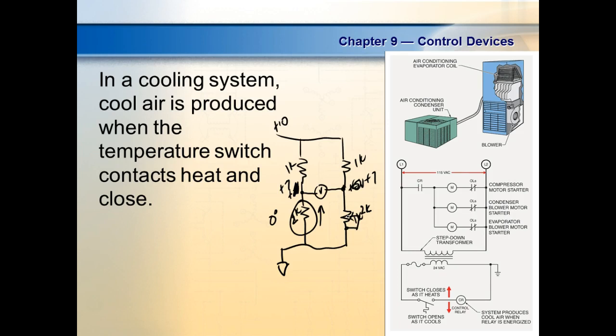And then if the temperature went down, my meter would measure minus. If my temperature went up, my meter would measure plus, because now the bridge becomes unbalanced. So it's a pretty important concept to understand in instruments. So we used to teach Wheatstone bridges when we got into series parallel circuits.